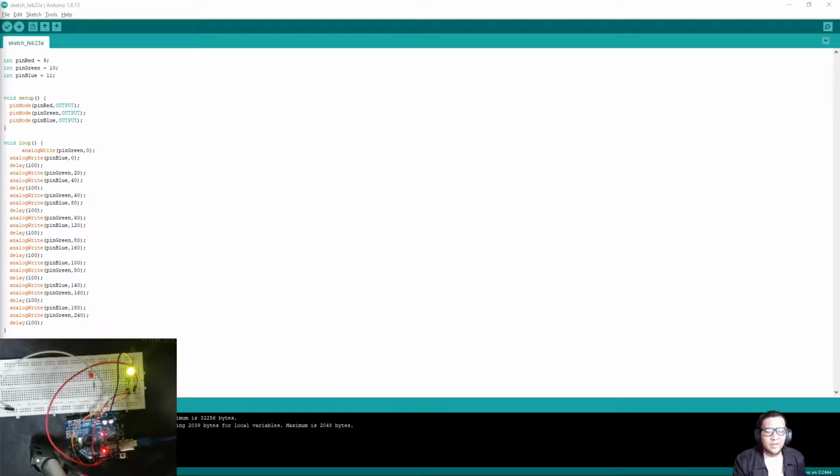Now we have everything we need with the exception of the jumper wires and resistors. Then we are going to look for the resistor, which is usually shown here in the basic components. What we're going to need is a 220 ohm resistor. So choose ohm, then type 220. Now we can try to recreate how traffic lights are being simulated. We're going to simulate our own traffic light.